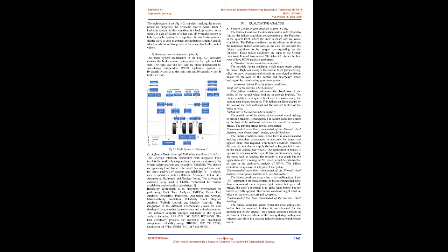2. Emergency wheel braking. Emergency wheel braking is when half of the normal wheel braking is available. In this case, either the inboard or the outboard brake system fails, then the opposite braking system, either the inboard or the outboard braking system, is available. In the emergency wheel braking, the anti-skid braking is available only in the one functioning set of brakes.